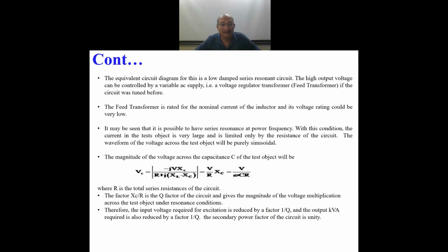It may be seen that it is possible to have series resonance at power frequency. With this condition, the current in the test object is very large and is limited only by the resistance of the circuit. The waveform of the voltage across the test object will be purely sinusoidal when you are supplying.